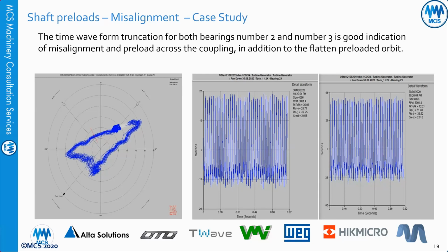When we ran the machine again, I thought I had made a mistake with the unbalance. Then when we ran the machine again, I looked at the spectrum and it was a subsynchronous peak, the whirling frequency, and it even transferred to become oil whip. The shaft starts the movement and then goes to the right and then to the center of the bearing. And we know that because we did a very good balancing job.